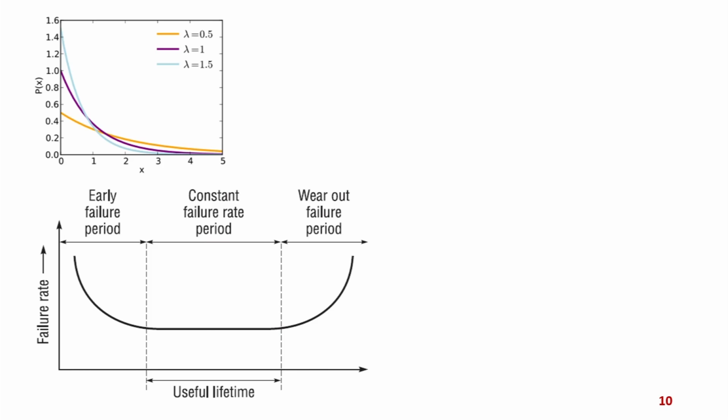So you see, for constant failure rate we had R(t) equal to e to the power minus lambda t. Whenever this lambda is a very small value, the life will be longer, since the failure rate lambda is smaller.